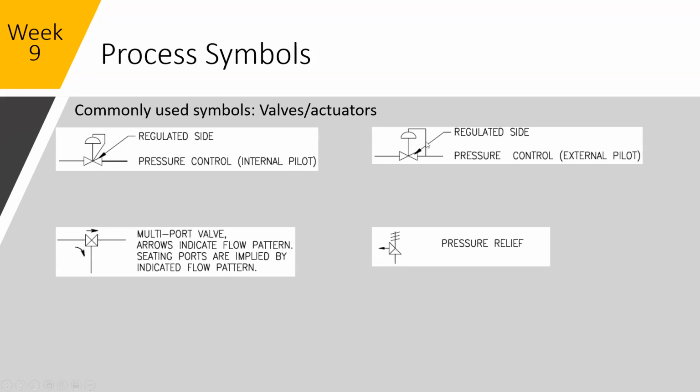So the pilot lines, whether they're for valves, pump control, pilot switches, a pilot line running to a specific spot is just kind of your control for that device, but not like a PLC control. These would be like a hard physical control for those devices.